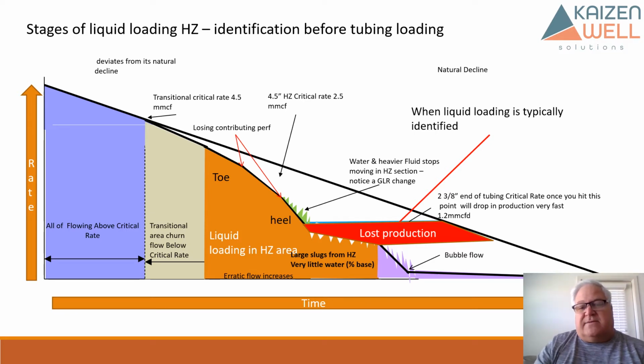And the other thing we've noticed is, the farther back up this side that we intervene, the production starts to go across. It flattens out. You change that decline, and it works its way over to this period here. So the longer we wait, if we're waiting down here when tubing is liquid loading, one of the big problems is that you've got a huge amount of built up fluid and you've lost a lot of energy to move that fluid, and it's very hard to get it going again.